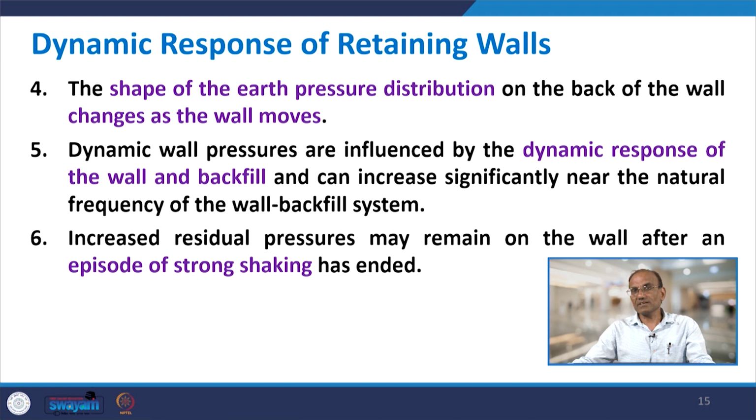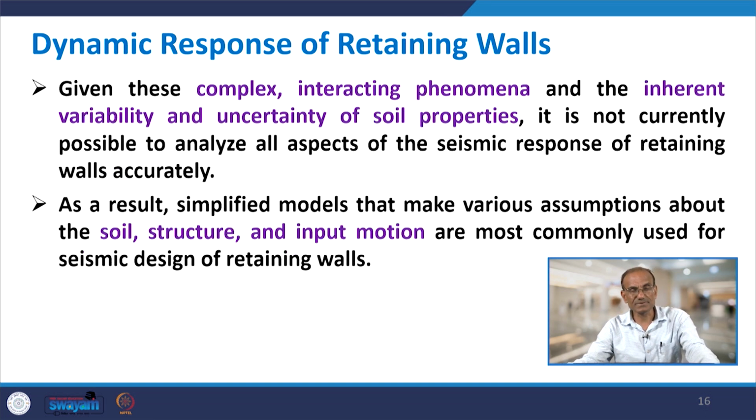Dynamic wall pressures are influenced by the dynamic response of the wall and backfill and can increase significantly near the natural frequency of the wall-backfill system. Increased residual pressure may remain on the wall after an episode of strong shaking has ended. So, this was the dynamic response.